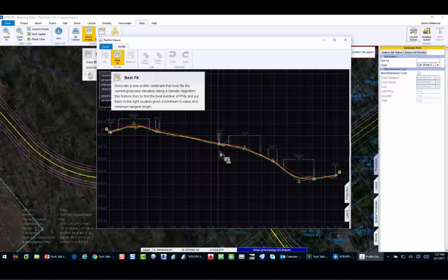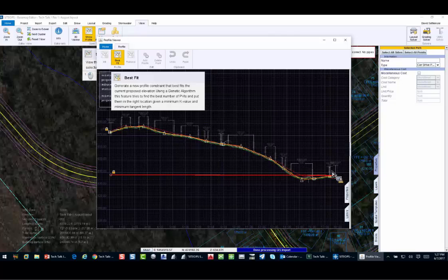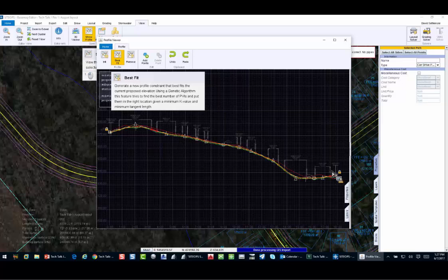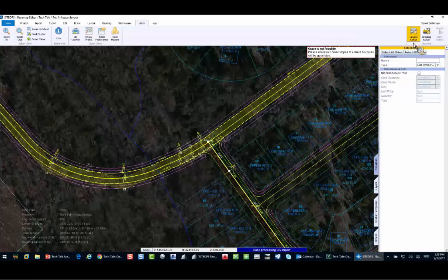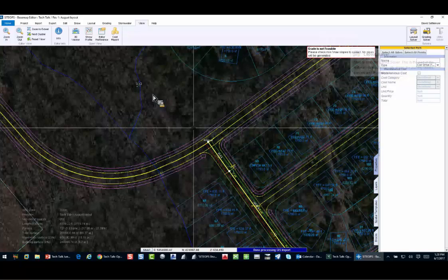As we're going through and talking about doing all these options, the more I can link things together, you'll see, for example, the little locks on each end. That means that this roadway links into that other master roadway multiple times. So as I change the major roadway, these will change with it. And then if I do the supplemental roads that attach to this one, so on and so forth, they all work together.